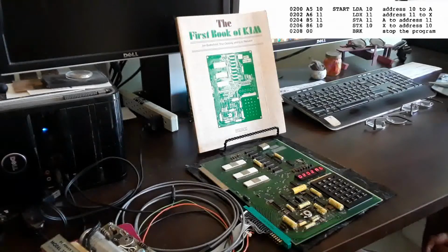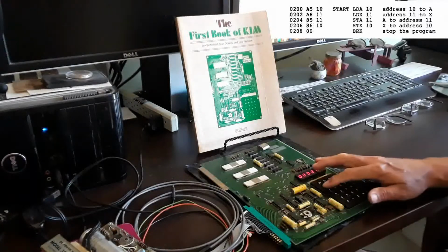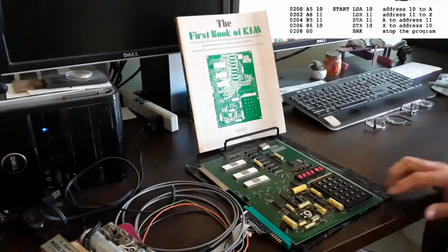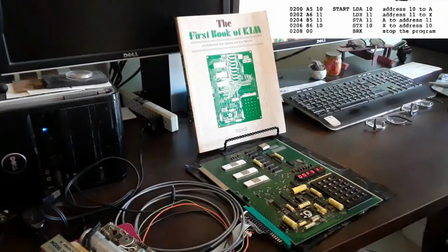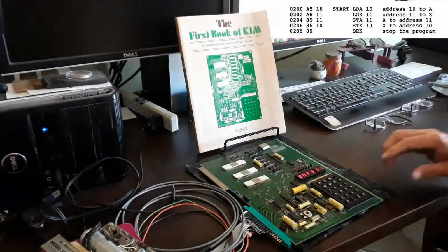So let's take a look at the data that we currently have in the various memory registers of the 6502 CPU. We can do that because the KIM-1 monitor program makes a copy of those registers and places them in memory so that we can view and edit those values. So go back into address mode and select address 00F3, which is the address that the KIM-1 uses to display the contents of the A or accumulator register. Here we can see the new value that we placed at address 0010. Now to get back to our program, we can simply press PC, which is for program counter key, and you can see it takes us right back to our program.